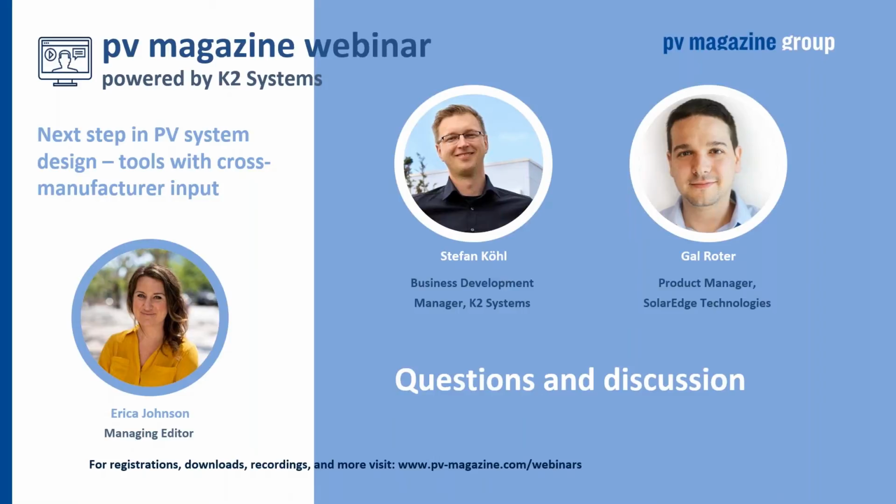So if you don't like to use the weather station, you can just simply upload a CSV file format, using either a TMY, typical meteorological year format, or we also support the PVSys format and our custom, very simple format where you just include for each day in each hour of the year, the weather values that we need for the GHI, DHI, and the ambient temperature. So you can just load it to the project and run using your custom weather data.